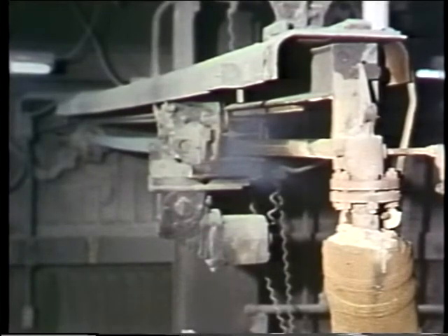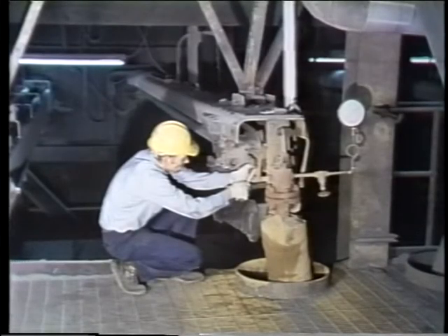The blowing medium cools the element, and if the element were exposed to boiler temperatures without cooling, it might fail. Leaving the blowing medium on might make the element a bit harder to withdraw, but it's got to be done. When you've got the soot blower back in its at-rest position, then you've got to figure out why it's hung up in the first place.